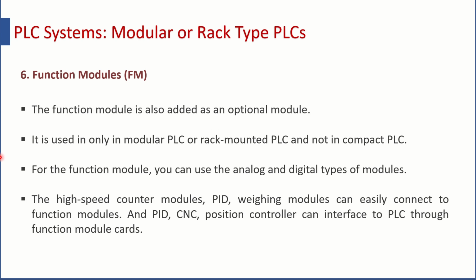The function modules are special modules and they can be added as optional modules. It is available only for modular or rack mounted PLCs, and normally such types of input or output modules are not there in compact PLCs. Okay, for the function module you can either use analog or digital type of modules because these are specialized modules.